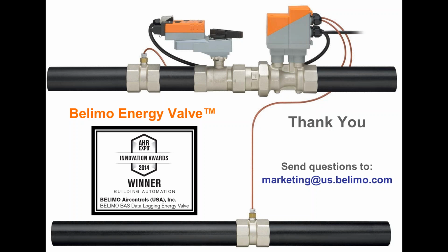In other words, if you have a 16-degree chiller and you're generating 20 degrees of delta T and that 20 degrees is showing itself to your chiller, you're going to get a reduced performance the higher that number gets. Now, I'm not a chiller expert, so I can't really tell you where the tipping point is, but typically when I work with customers, we're trying to match the plant is the goal.